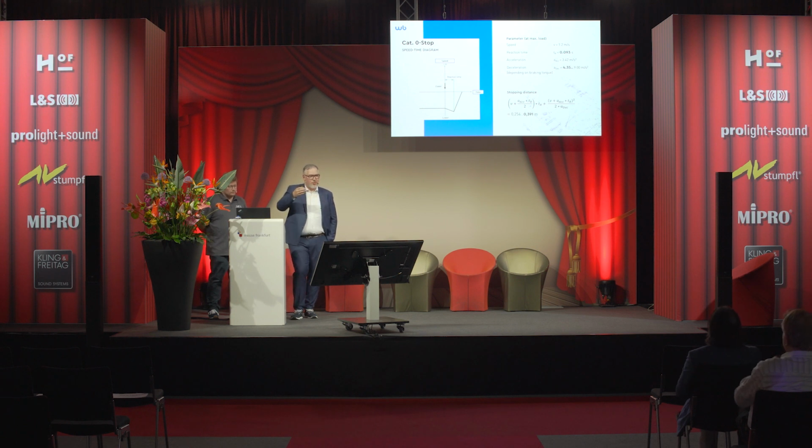In this time, the motor is even speeding up. And then the brakes apply, and you have a given stopping time. So depending on the brake torque that you have in this consideration, you would have something between 4.35 and 9 meter per second square deceleration. That is the deceleration at maximum load. With minimum load, same again.